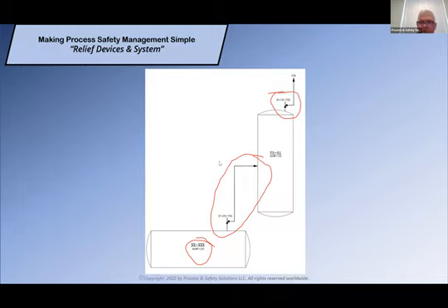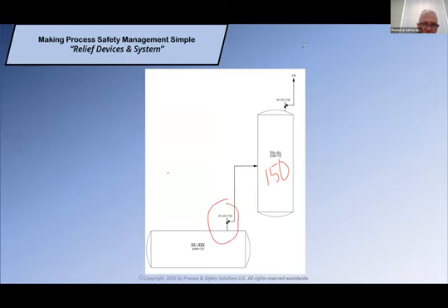So I have a fire case, and I have a fire here. This pressure here is going to be 150, and this relief set at 250. So it's a conventional relief valve. It's not going to lift until, when? 400 PSIG before this lifts, probably in the catastrophic range where we could see catastrophic failure of that valve. So making sure that we understand when to use the right valve.